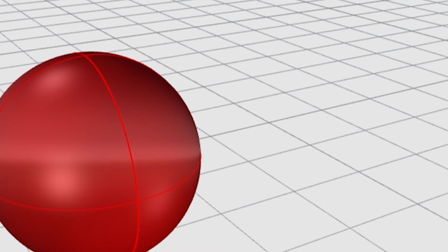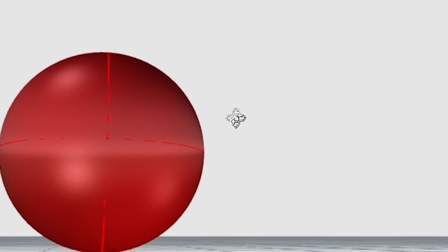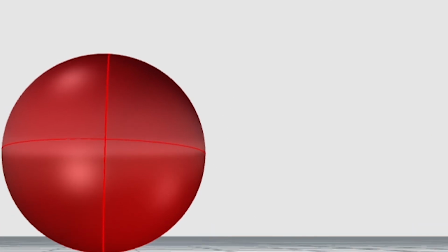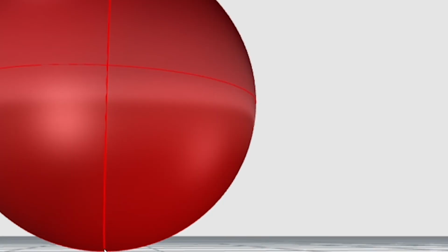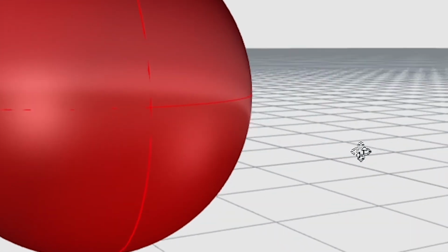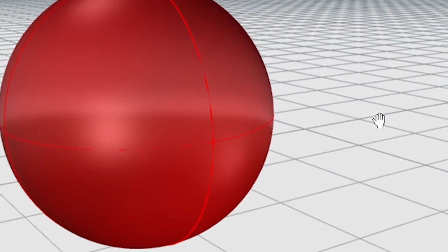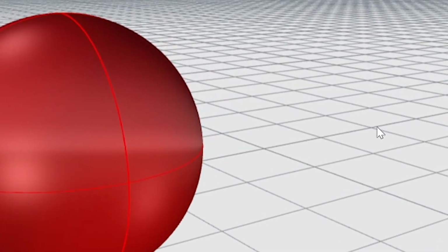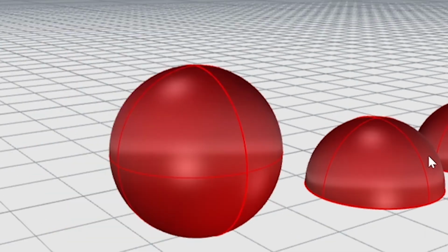It's pretty crazy, actually. But sometimes we need to set the print up for success by splitting parts that aren't stable on the bed. Imagine a sphere. It's printing one layer at a time on this bed, and that first layer is only touching the bed at a single point. Now, can it build a scaffold to hold the side walls up? Yes, it can. But another way that we can dramatically increase our chances of success is by doing something like this. We just split that shape.